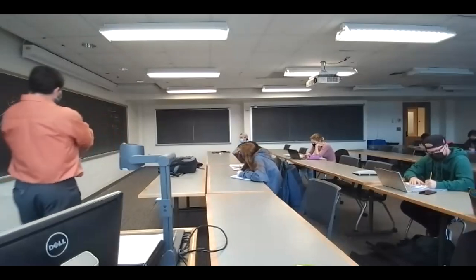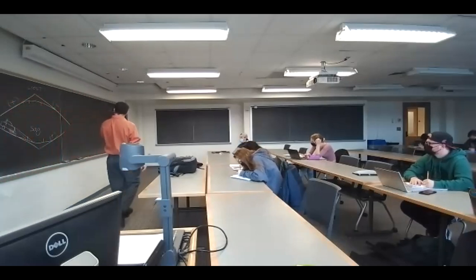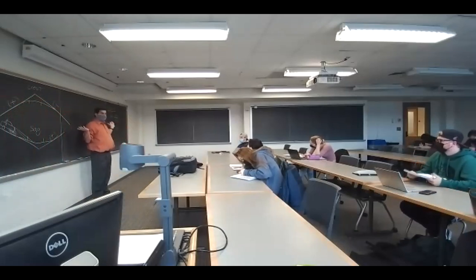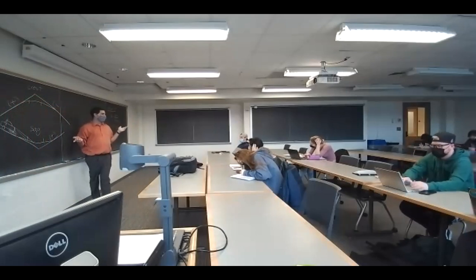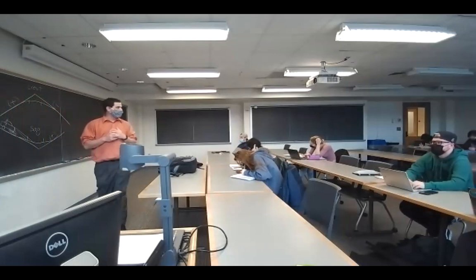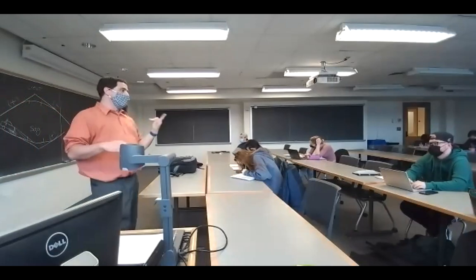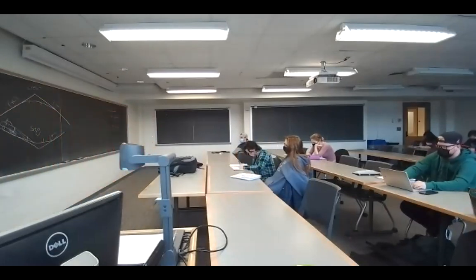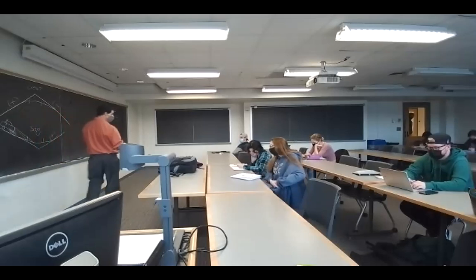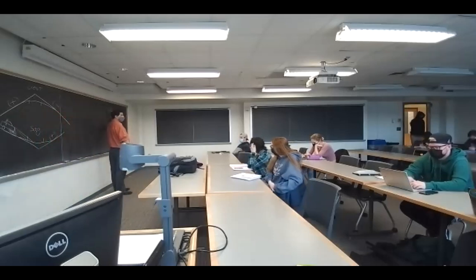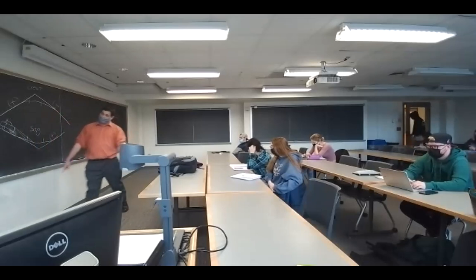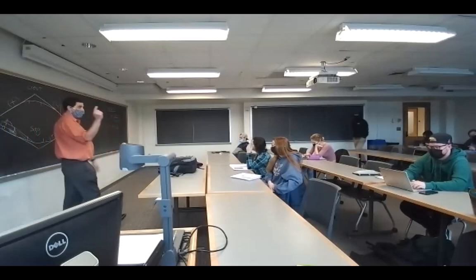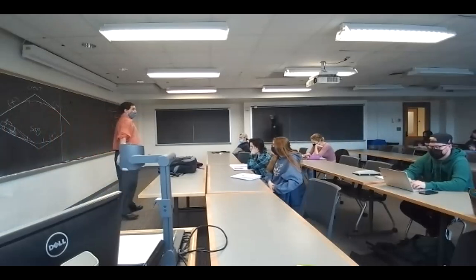So next class, we'll do maybe a couple examples of this. Pretty basic algebra, nothing really too complicated. Just knowing where to plug the numbers in and what this is giving you. So if you wanted to know the low spot elevation wise, you would take that horizontal position and use that over here for your X. So the X can be anywhere along that curve if you want to copy.